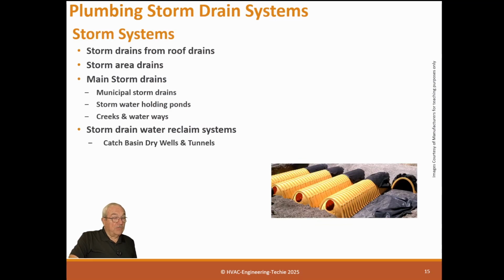You have catch basin and dry well tunnels. So these are tunnels, and what they do is they put these plastic tunnels in, and then they cover them all with gravel. And then the storm water feeds into these tanks, and these tanks don't have a bottom in them. So they seep in, and what they're trying to do is maintain, and these have perfs all through it, so that they hold the water and let it slowly drain and perk to the earth.